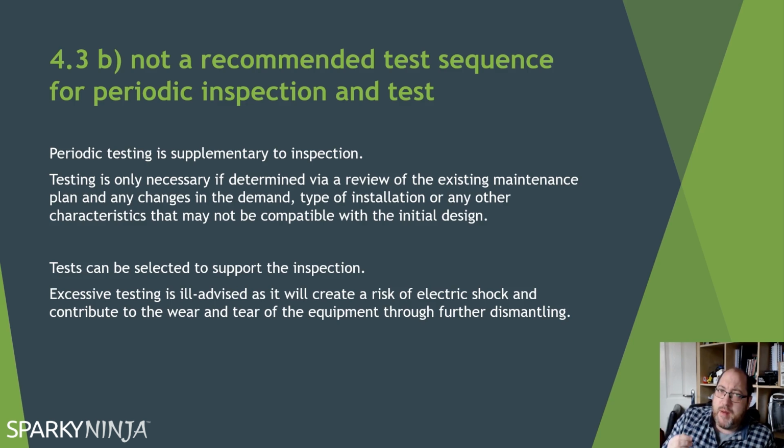But what you need to remember is the whole idea of periodic inspection and testing is to use your inspection skills, your ability to see an existing system, to assess it against the current environment, to assess it to be used for the future in that way that you're seeing it. So a change of use, a change of ownership, a change of demand, is it still suitable? Is there age? Is there wear and tear? Has there been a flood? Is it still suitable to carry on being used?